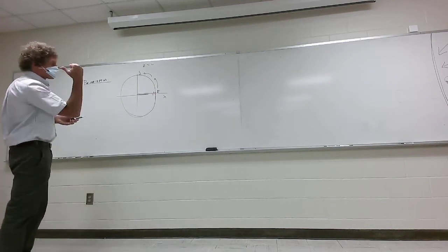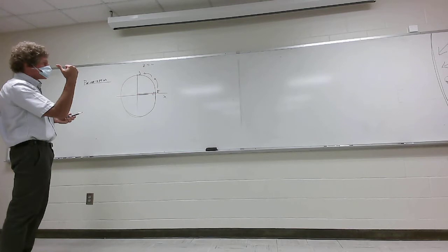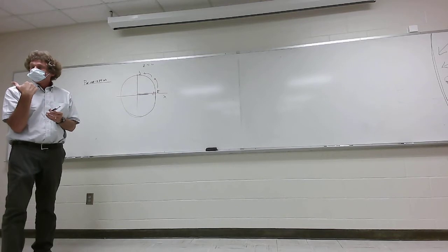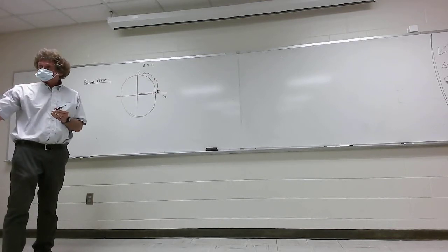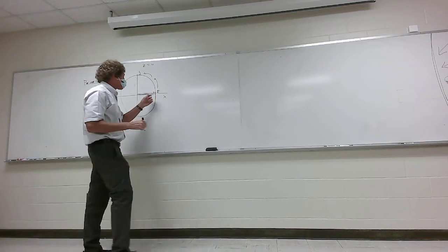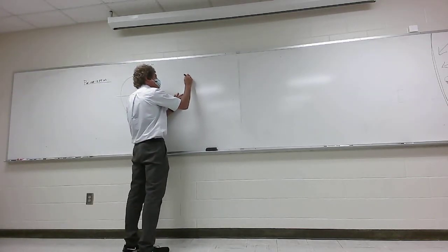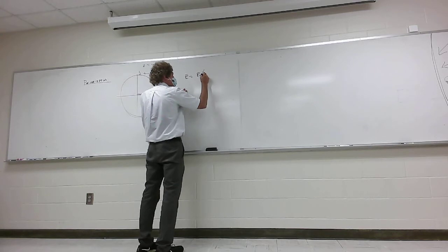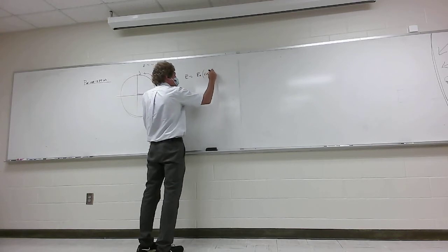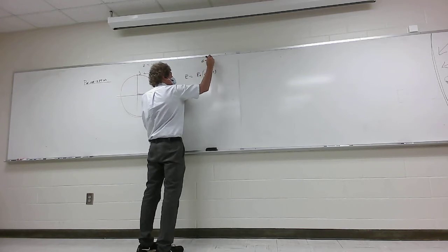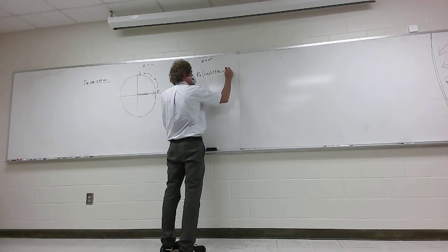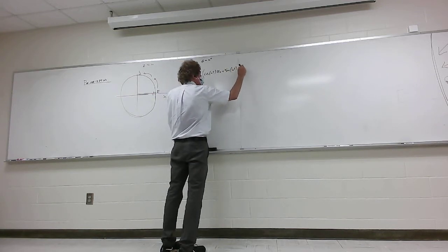So if we put our thumb in the direction of propagation, I'm saying it's coming out of the board, then the E field would be going this way. Y'all follow me? That's actually called right-hand circular polarization. I'll get to that in a second. But first, what would be a mathematical way of describing this at z equals 0? Well, I could say it's really just what? Just think about what I'm doing. E naught here, right? And it could be cosine of omega t. Really, theta is omega t. It's the argument of cosine. And that could be ax plus, and then it could be sine of omega t ay.